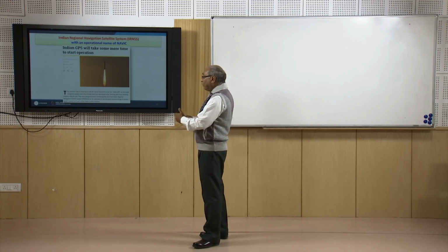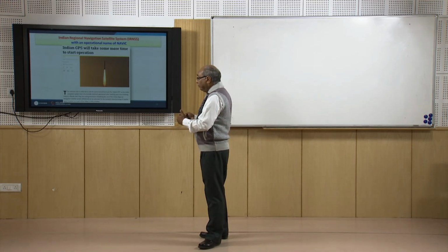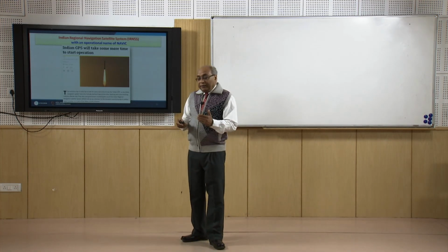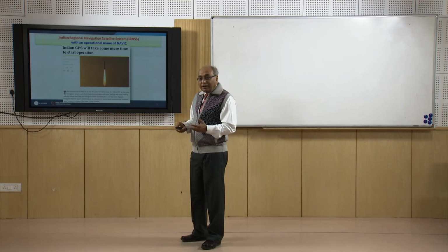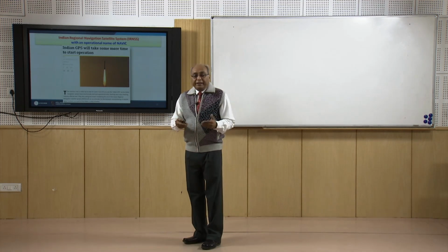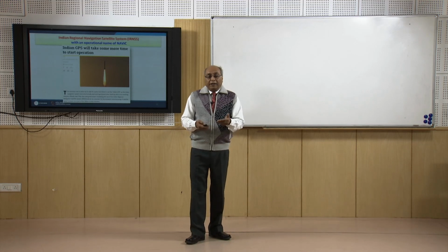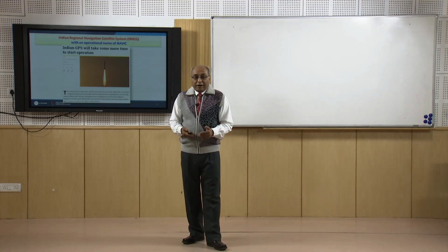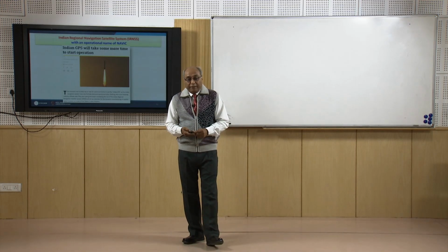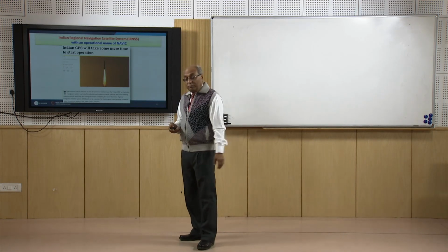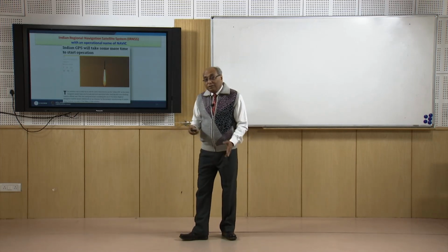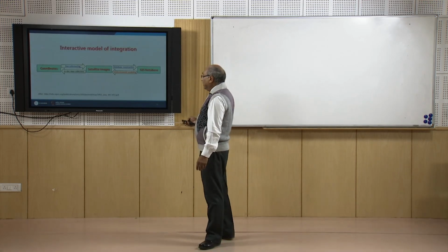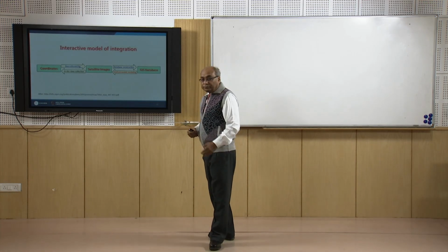So that is the advantage for us: if we start getting signals from many navigation systems of the world, then our position estimations are going to be very accurate. Generally with these smart mobiles, we get a position estimation with an error margin of maybe 5 meters or 10 meters sometimes, but if I am getting signals from 3, 4, 5 navigation systems, that accuracy might be improved even to within 1 meter, which is very good for many applications.